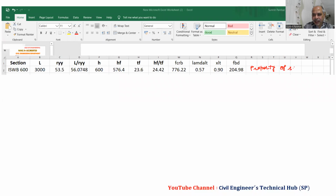Property of the section. Today we will see tentative values, and accordingly we can consider the value and solve the problem. Now I have considered ISWB 600, and let me take the length as 3000 mm, because the others are constant; we change only L for a particular section. From this we have calculated L by Ry, and then we have hf. hf equals h minus tf, because it is the center to center distance between the flanges. Then we know hf upon tf. These two values are important to calculate the value of fcrb.